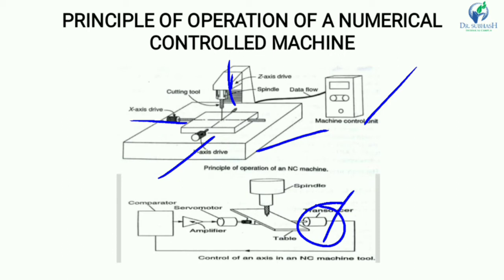The Z-axis feedback transducer ensures the correct depth and feed rate. The drill is then withdrawn to the desired height and the machine starts the positioning movement to the next location of the drill. This procedure ensures the production of an accurate workpiece.